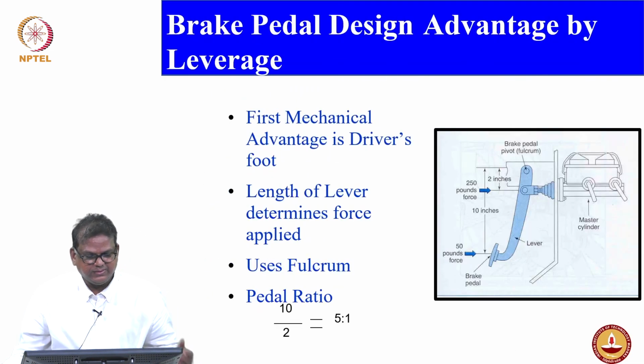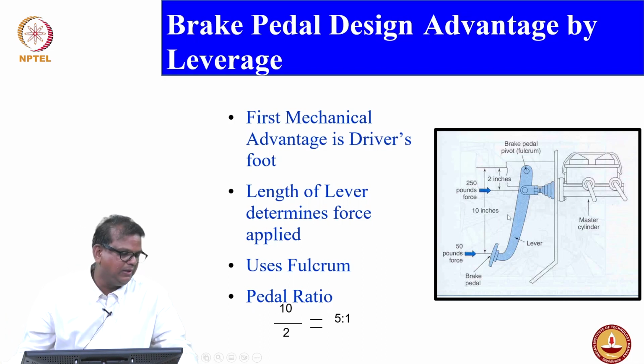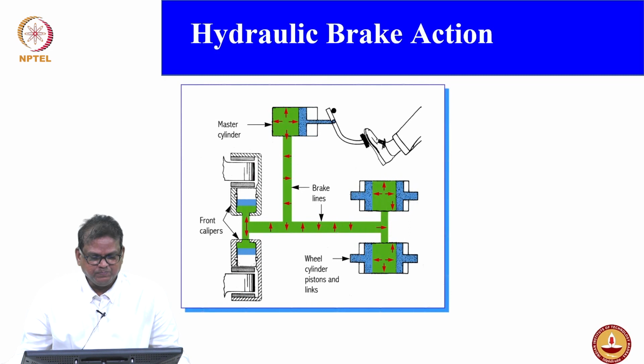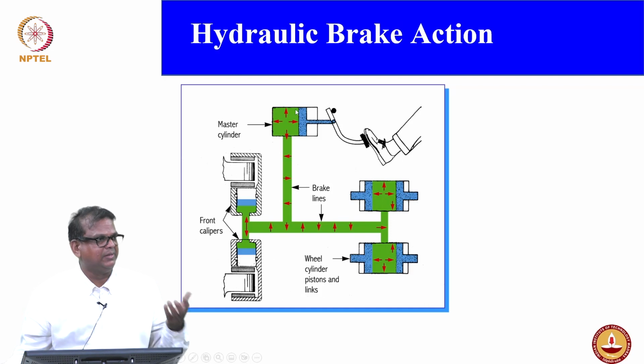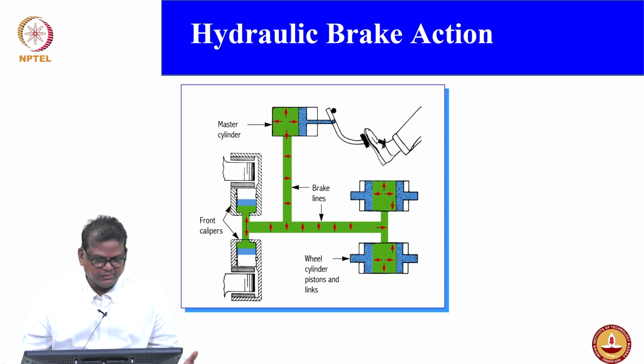And this is the brake pedal design advantage. Normally it's a lever method. If you give a small effort, due to the lever method, like a momentum, it will enhance the effort. That's one aspect. Another is hydraulic. Instead of applying only mechanical force through the pedal, the fluid will generate the pressure and activate the caliper as well as the drum brake system. This is happening through the hydraulic brake system.